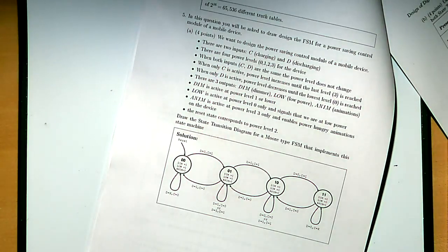Another part that is interesting relates to Lab 4. I hope some of you still have a memory about what we did in Lab 4. Okay, so what we did there is we introduced these clocks into our circuits. We did synchronous circuits where you have blinking lights indicating which direction you want this Thunderbird car to turn, right? And remember in that lab, we asked you to design a state machine for this. You're representing your design using a finite state machine. And the transition between different states in this machine corresponds to the different inputs that the users give, okay? And at the time, those were triggered by the clock.